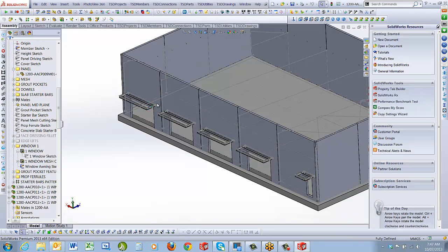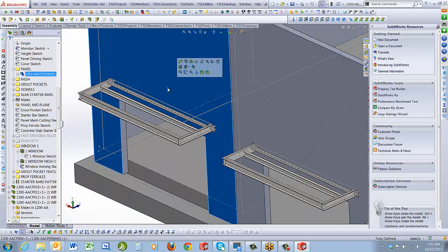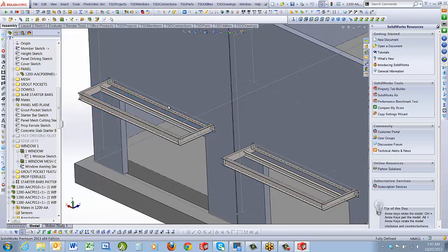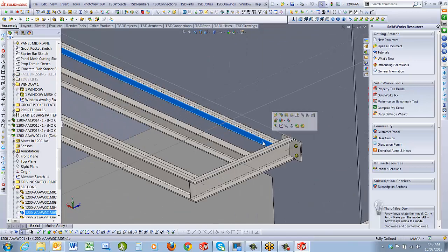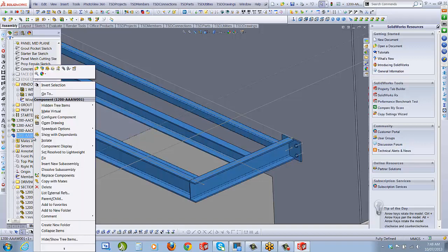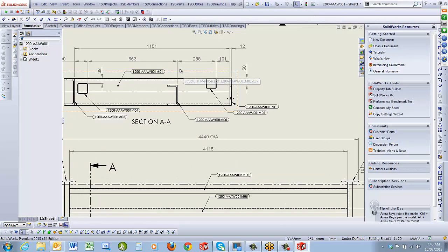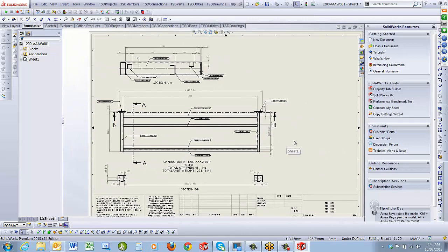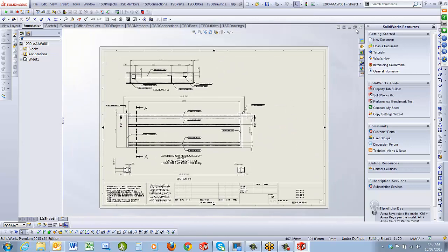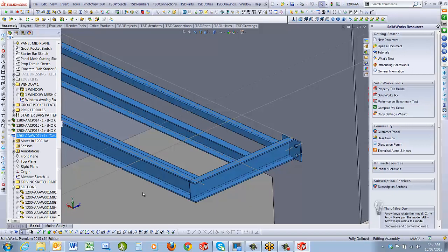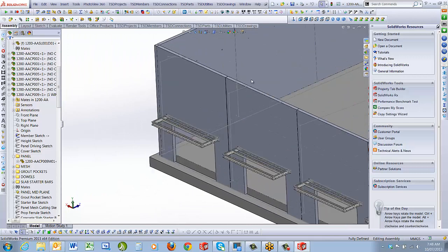Now, I've only punched holes in this panel here, so I'm only just going to go through the process of locking. Okay, now if we have a look at this awning, I just want to show you that the awning is fully detailed. Right, there it is, got all the details associated to it, all the mark numbers, dimensioning and everything. That awning's ready to go. Might just tidy up a couple of the dimensions through the adjustment process, which you can see here. There's some dimensions here that might need to be modified, and just save that. Okay, let's lock this panel.